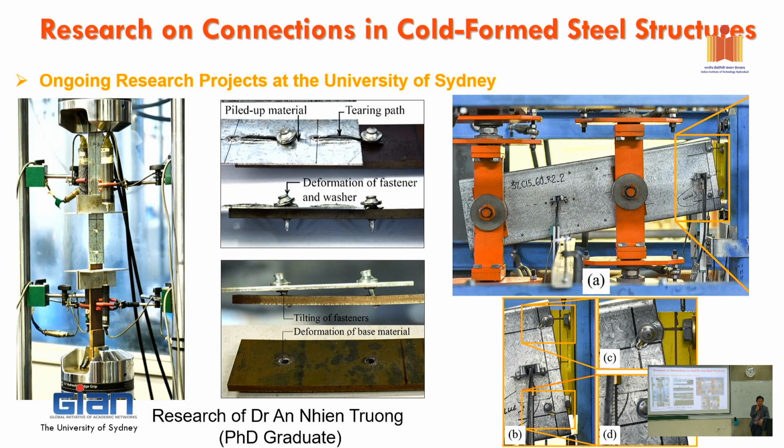But we test a lot of connections. It's very hard to get to the fixed end. We tested already with cold-formed steel, and as long as you make it very, very stiff, so you have a big plate on the top, a big plate on the bottom, and you screw a lot of screws on the top flange and the bottom flange to carry the hogging moment. Otherwise, if you just bolt it on the web only, as in normal practice, you're not going to have a connection that can carry the hogging moment.